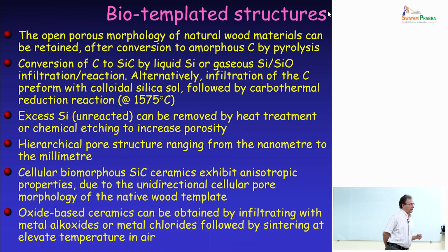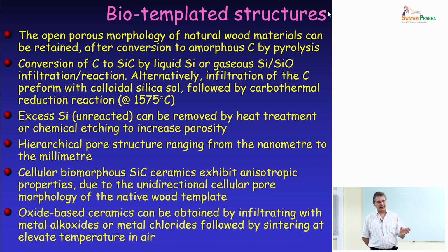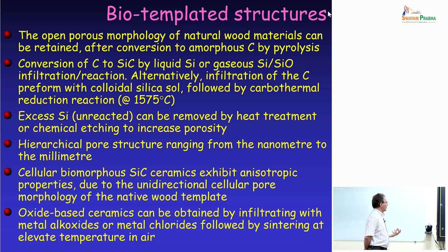People have also realized that, as I mentioned, in nature you have a lot of highly porous structures, and you can, of course, take inspiration from natural structures in order to come up with architectures that have enhanced functionalities. People worked on making ceramic foams using a biotemplate. They started using wood, for instance, infiltrating the wood with ceramic particles or ceramic precursors, and then burning out the wood to convert everything into ceramic material. In this way, you can obtain the benefits of the original wood structures.